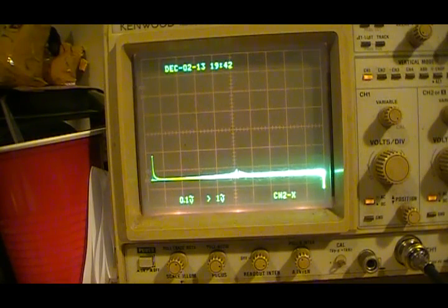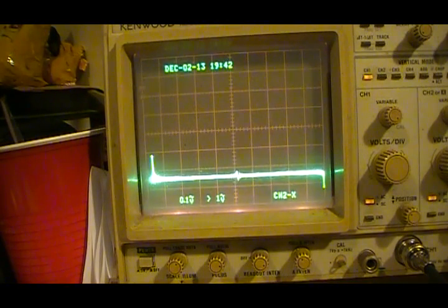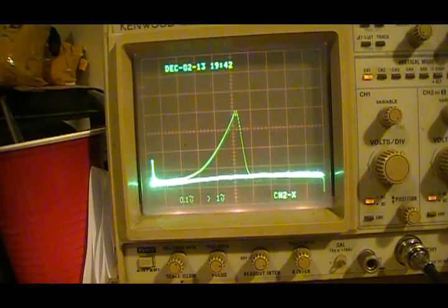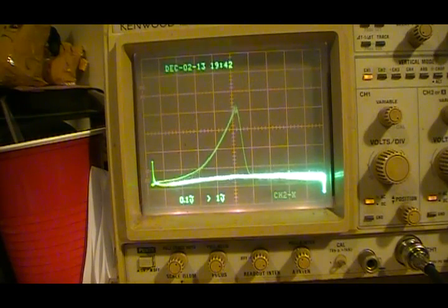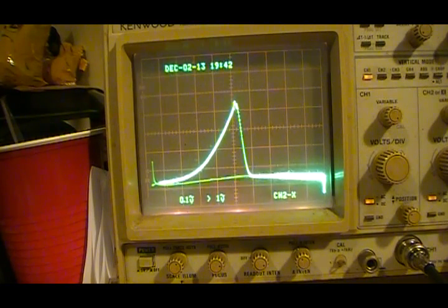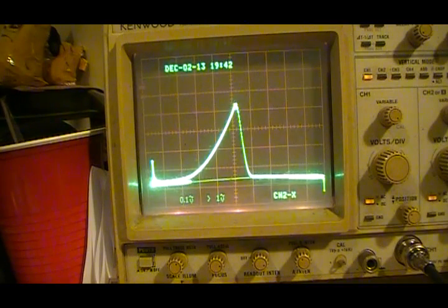Interesting. My cable's losing some strength there. I think we're going to have to be fixing some cables eventually. There we go. Now the top side, adjust it a little bit, and it really changes things. We peak it so we stay on frequency. That's how come we want a marker, because sometimes they don't really max peak out at 10.7